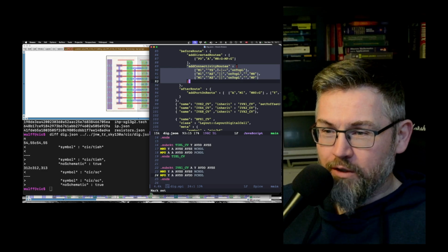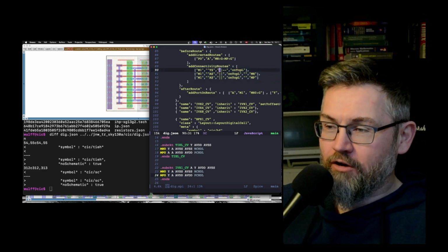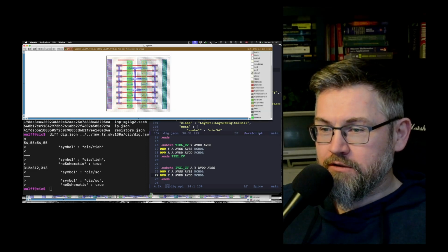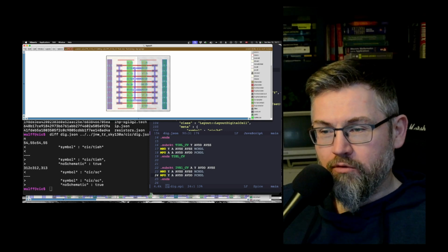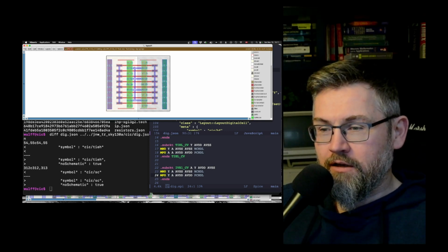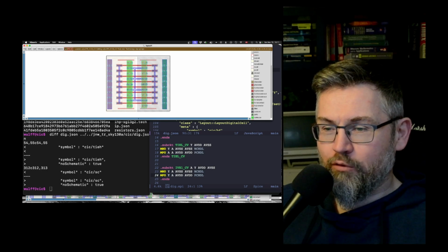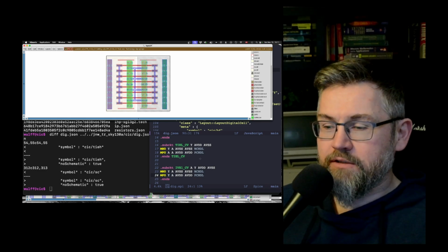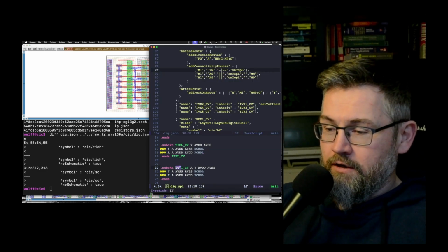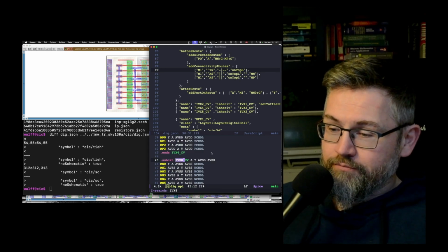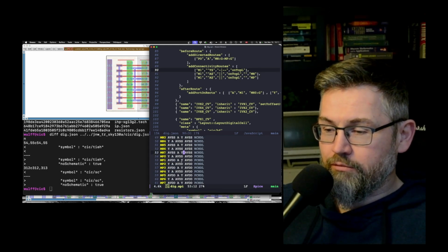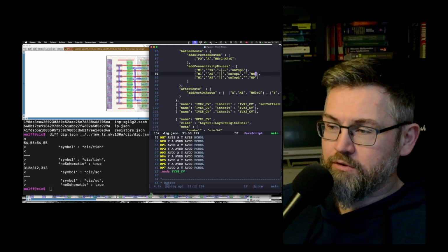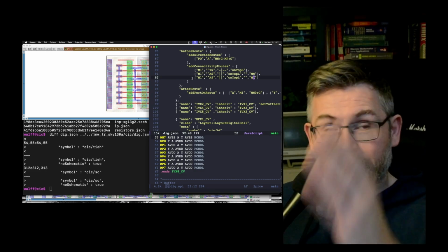So I've only defined it once, but then it knows, okay, start on top left, that's the on top L command here. So that started this rectangle, go out, and then route in a down, bottom, over pattern for all the Y's. It knows the Y's because that's in the spice files, right? X1, X8. Here it can find all the rectangles on the Y's and then route those. And the same for the A's. And it says, okay, for the NMOS side and for the PMOS side, route vertically.